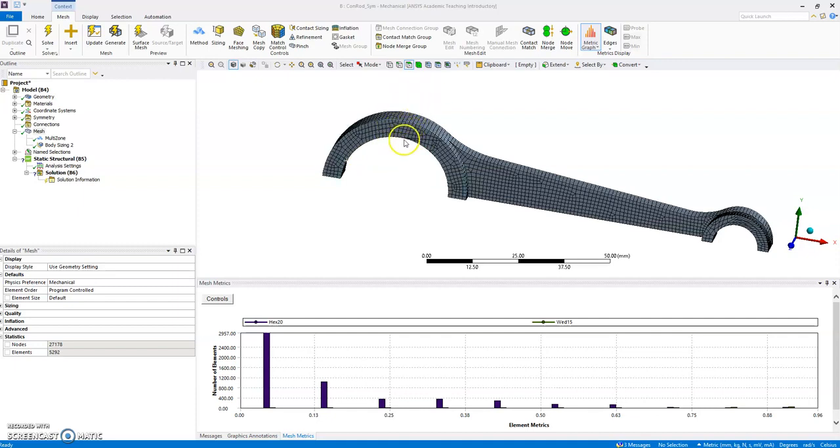Very likely this should be cut. There should be some bolts to join two halves of that head here. But so what are we simulating? Which loading are we going to apply here? And often choosing the correct loading is actually a lot more difficult than it sounds. Sometimes the boundary conditions are pretty obvious, but sometimes they are not so much.